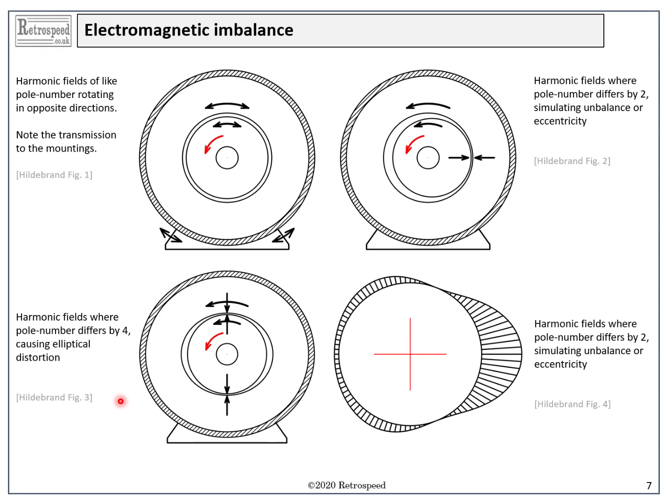So we can approach the problem of noise and torque irregularities by investigating the harmonic fields in the motor, and the place to start is with the stator MMF harmonics, because these can cause parasitic torques even with a perfectly smooth air gap.